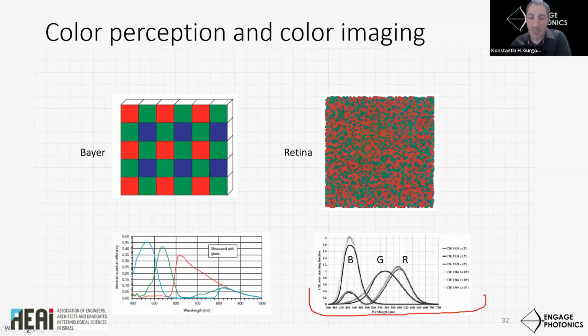To be able to acquire a color image, a color filter array is applied onto the image sensor by the manufacturer, making a periodic mosaic pattern of pixels sensitive primarily to red, green, and blue wavelengths. So you can see the spectral sensitivities or transmission of these filters.